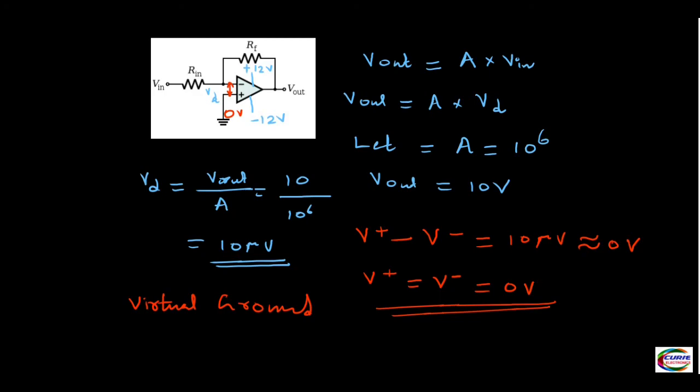That's all. Both the input terminals are going to have the same voltage. That is what the virtual ground is. It doesn't mean that there is no input to the amplifier. There is input. That is what the 10 microvolt is. That's an input, so due to the high gain, it will get amplified.